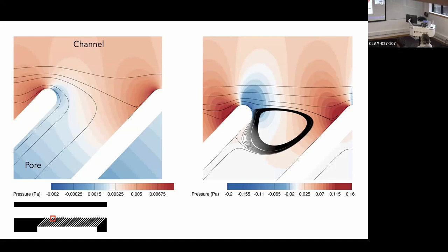I think the pumping should be similar, right? Because we've looked at the parameter regimes of where you might be pumping. The question is how small can this go, right? So here we're filtering out particles that are maybe 20 to 100 microns. Whereas in Deer Island, you do have to take things out that are smaller than that. So you might want to do this as a first stage and then put it through a finer filter.